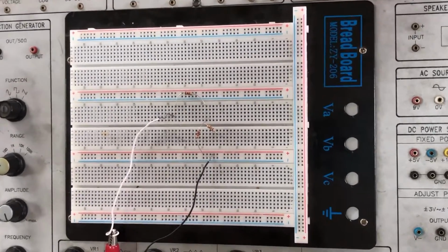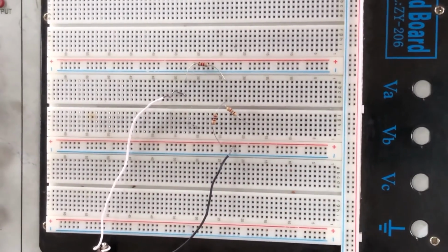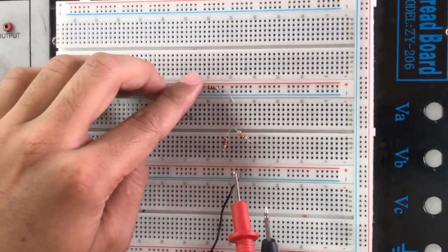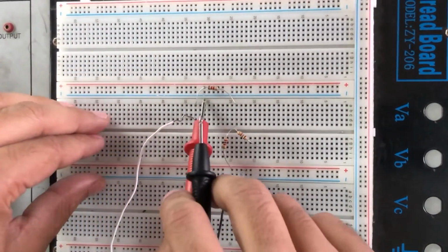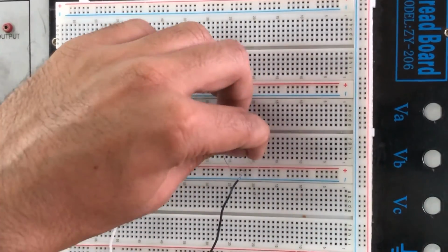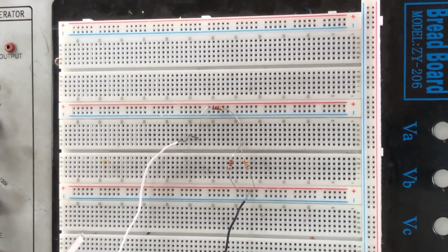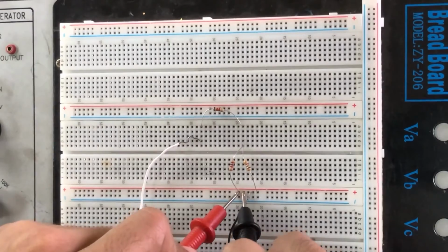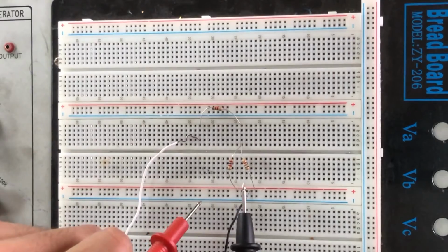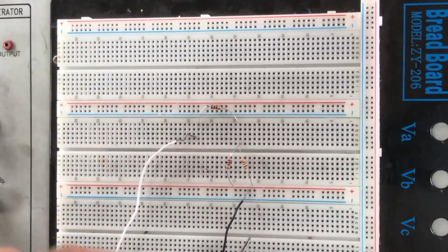By this experiment, what we have concluded so far is that the current flowing in our circuit is directly proportional to the voltages that you have provided to your circuit. If we increase our voltages, the current also increases. And also we have checked that the current passing through R1, that is actually the main current that we have designated by I1, was equal to I2 plus I3. Actually, the current flowing through I1 was 2.2 milliamps, and then the current passing through R2 was 0.8, and the current passing through R3 was 1.3. So whenever I sum up 1.3 plus 0.8 milliampere, it will be around 2.2 milliamps.